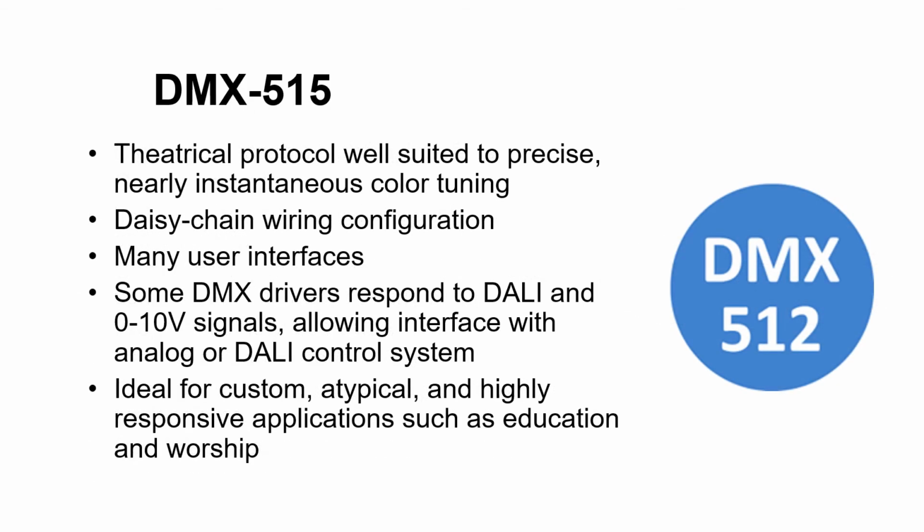Originally designed for theatrical applications, DMX has the digital capabilities needed to address and send multiple signals to an individual luminaire to control color and intensity of multiple LEDs. There is an almost instantaneous response by the luminaires to the control signal. DMX is capable of two-way communication if this feature is desired and enabled.